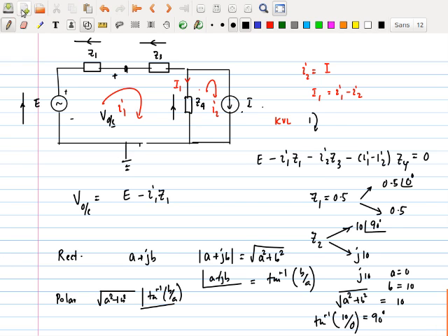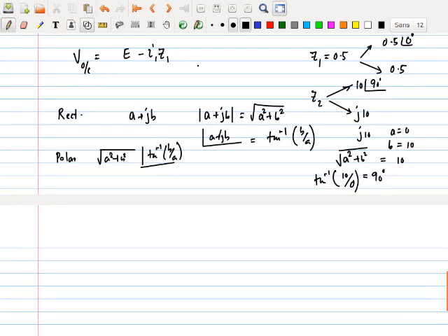Okay, there you are. Now after I do all of this, what I have to do is say that that was Z2, this is RTH, and that is V open circuit. I put back the RL into the circuit. So I have brought the entire circuit down into a single voltage source with a resistance. Right? Good.